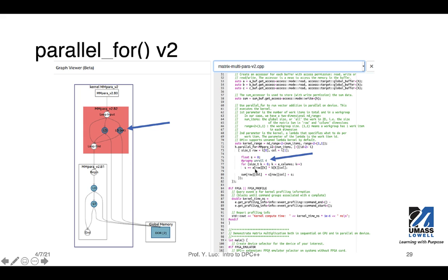So essentially, we are using this unroll factor of 4 to increase the number of load units from 1 to 4. So that's why you see 4 here, so that we can load 4 of these vector elements from these rows or columns, instead of just loading 1 at a time. So essentially, the number of loop iterations is going to be reduced by a factor of 4, but each loop iteration will use 4 times the resources before the unrolling.